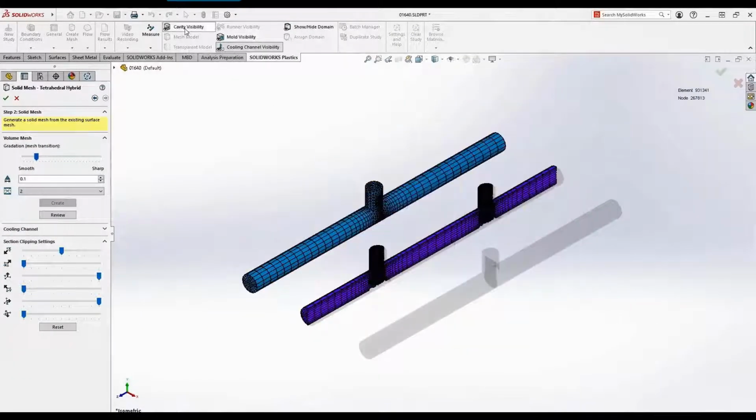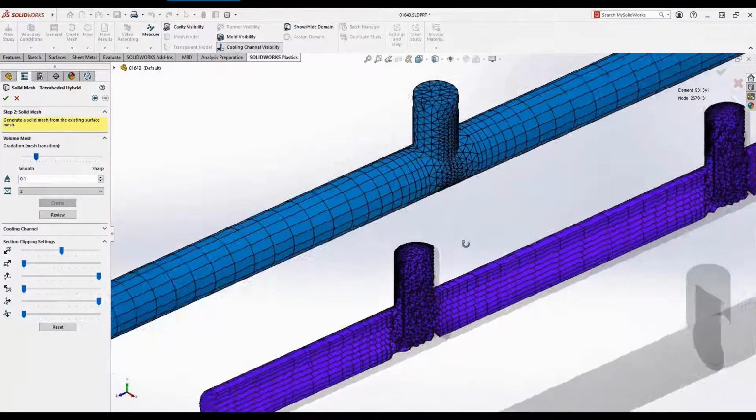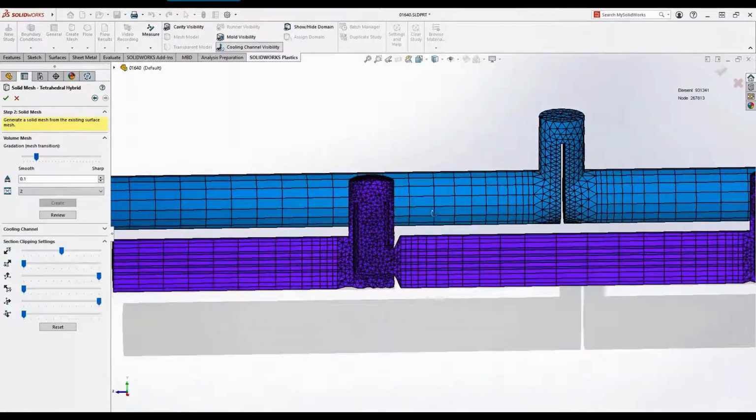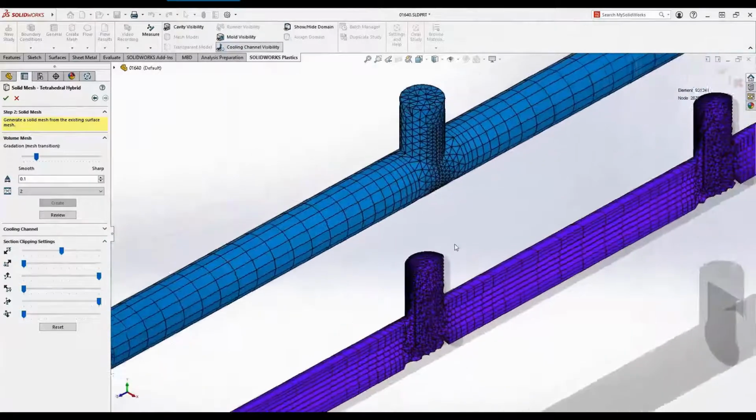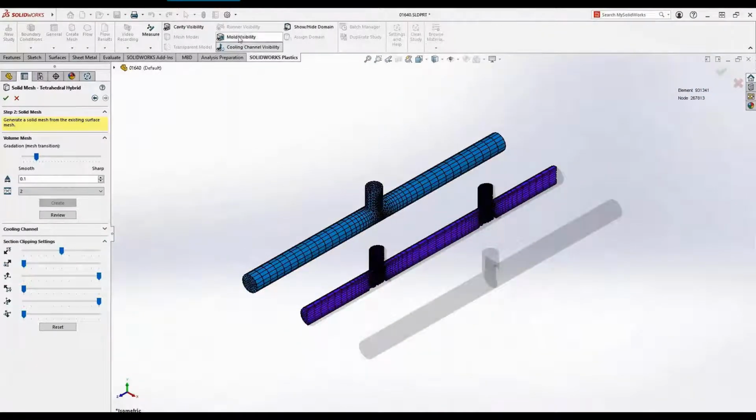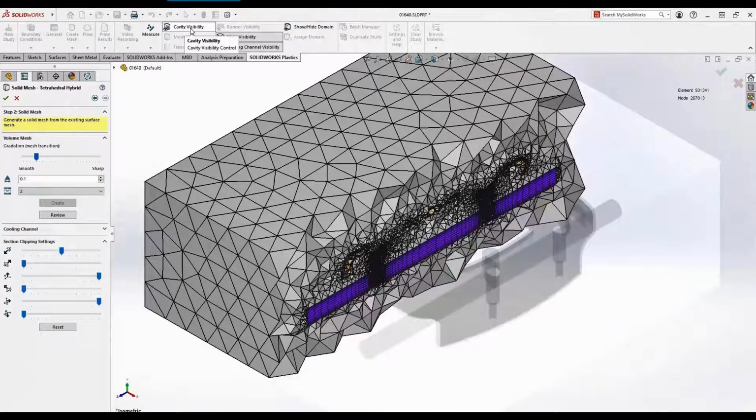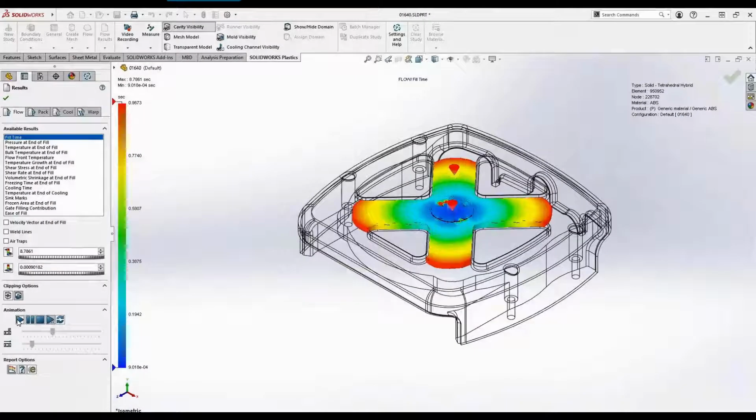The entire plastics analysis has been defined geometrically and virtually. This makes the file on disk smaller, portable, and more adaptive to change. Eventually, when you do mesh the model in preparation for the final simulation, you'll be able to immediately see the benefit of those improved baffles and bubblers defined earlier.